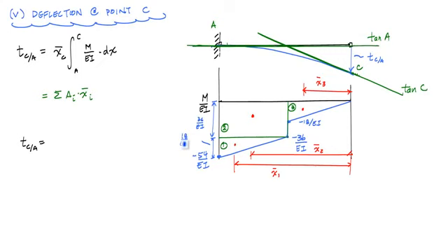And so the area here of the triangle is 1/2 times negative 18 over EI times width times the arm, this x bar 1, and the centroid of a triangle is 1/3 from the fat side, so this distance right here is 2 meters, which makes x bar 1 2 meters plus 3 meters, which is 5 meters. So the arm is 5 meters.